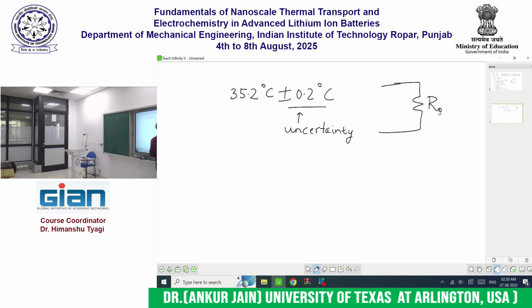So here is a resistor R0, metal resistor. Okay, keep in mind not the colorful resistors that you see in electrical labs. Those are carbon-based resistors, and they have been designed to be temperature insensitive, because they want to put them on a device and then in a car perhaps, and as the car goes around, you don't want those resistances to change with temperature, right?